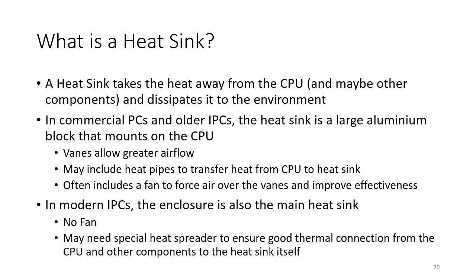You also see heat sinks with heat pipes. Heat pipes can be used to better transfer heat from the CPU to the heatsink. It's a bit like in your fridge, there's a heat transfer mechanism based on liquid inside pipes. So the liquid heats up and turns to a gas and then moves to another area of the heatsink, which can then give better heat transfer. And then from that part of the heatsink, that gas cools down back to a liquid, and you get this continuous circulation, which gives you better heat dissipation than just using pure metal by itself.